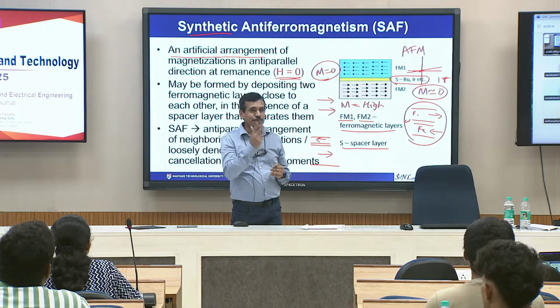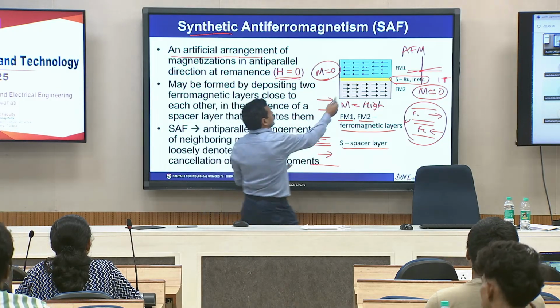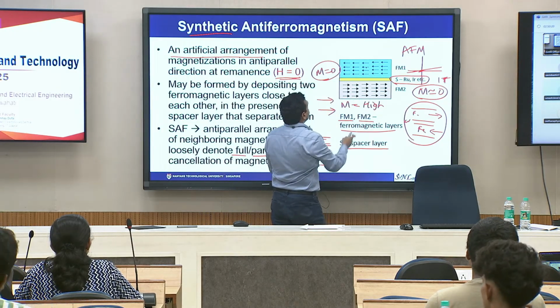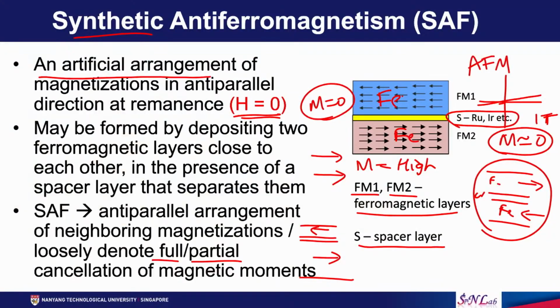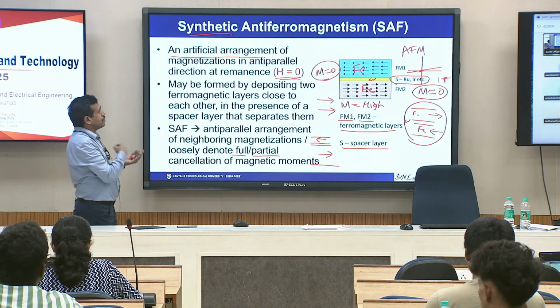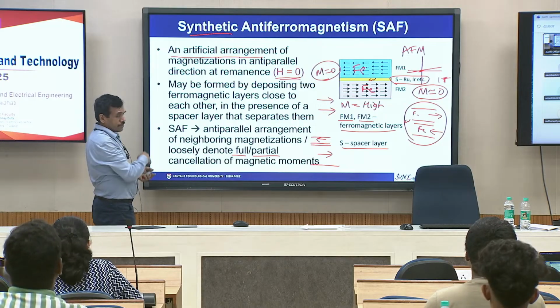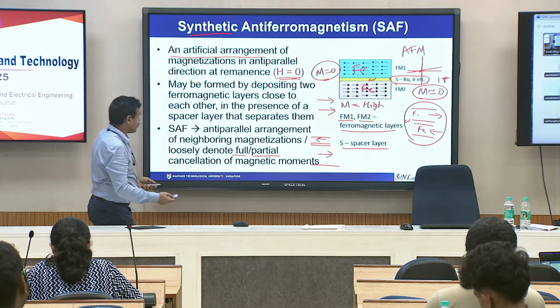At least 2, yeah. So, you can use the same ferromagnetic layer, for example, say iron, chromium, something like that, or cobalt, ruthenium, something like that. So, you need at least 2 targets and at least 3 layers to make a synthetic antiferromagnetic structure.